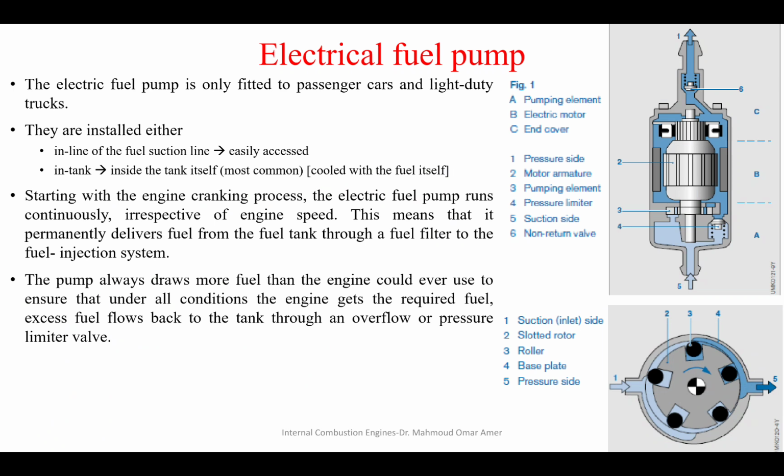As for the electric fuel supply pump, it can be installed either in line or in tank. Some pumps are installed in line, and some are installed inside the tank itself. It operates electrically with an electric motor inside the pump itself. So whenever you start the vehicle, the pump starts right away.